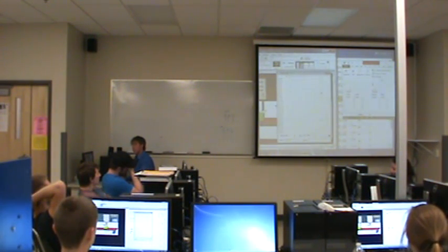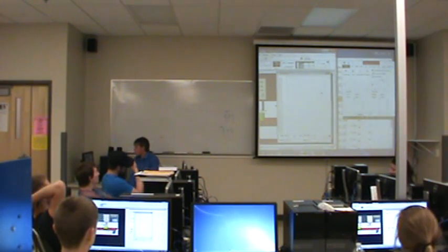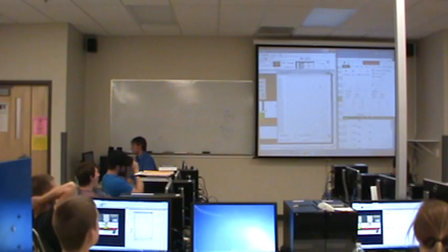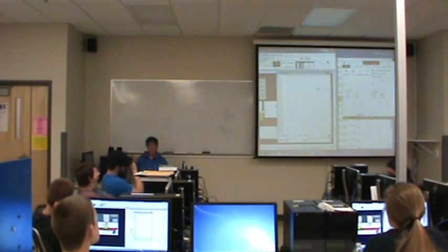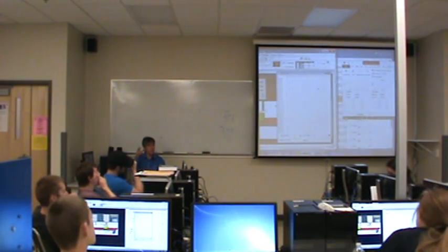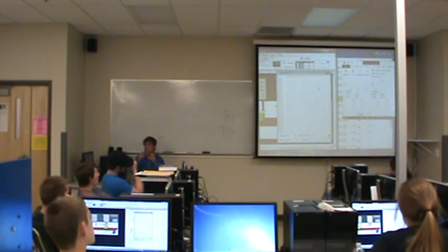Now if I run the program, the mask moves are going to completely obliterate this. So we'll fix that in just a second. Okay? But for right now, that's the data that I need in memory that I'm going to compare inputs to. So I'm going to compare a whole word of inputs to a whole word of binary data.